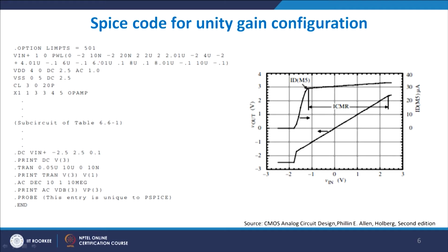You get a VDD, as I discussed with you again, but here you use a dot AC because you are giving an AC cycle, across a 10 mega ohm resistance, and then you are trying to find out the transient value of the voltages at every particular point.